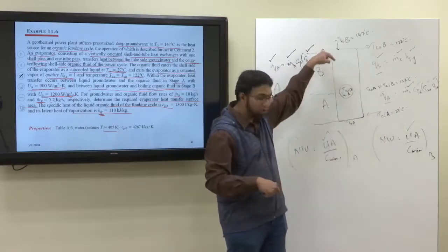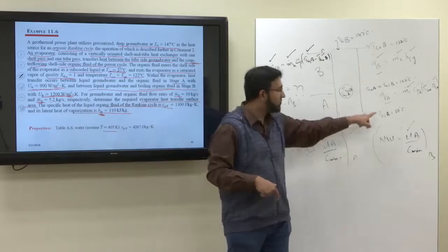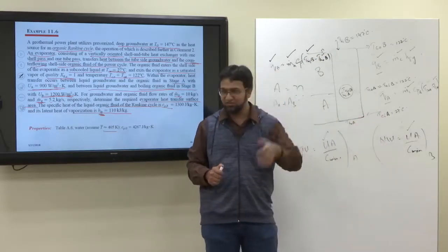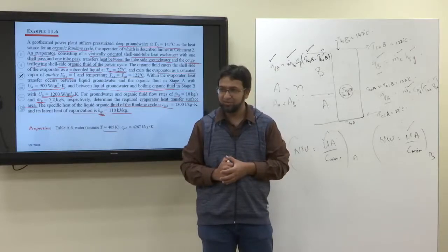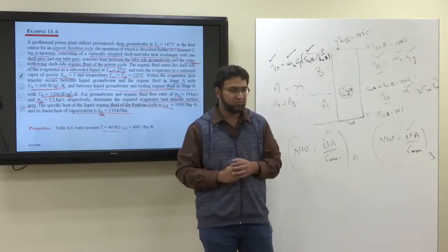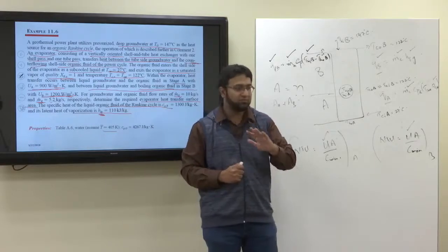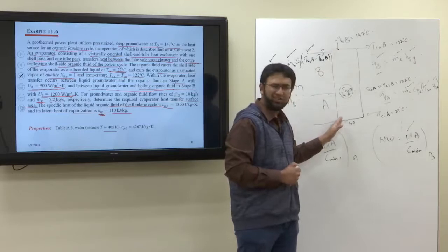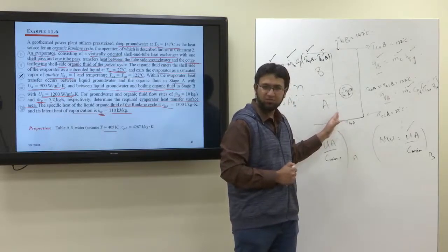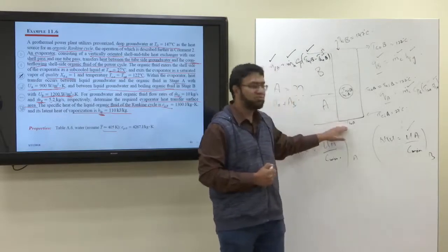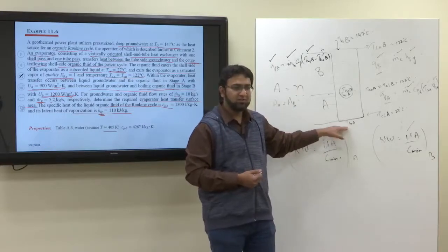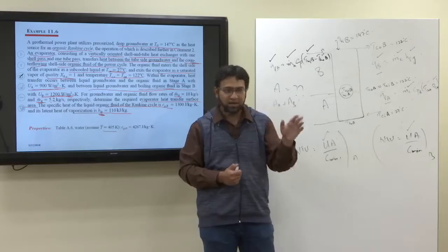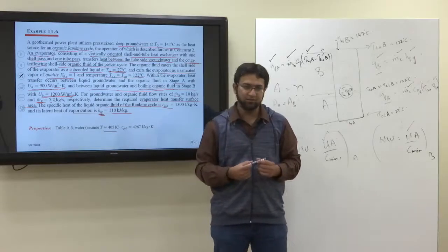Okay. The temperature will drop, but it cannot drop below 27, right? So suppose you take it at 28. Okay, so that's good enough. But what they took is that they took 147 to 30 degrees less, which will be 117. So they assume that the outlet is at 117. So the average will be in between, and that will be approximately 405 Kelvin.